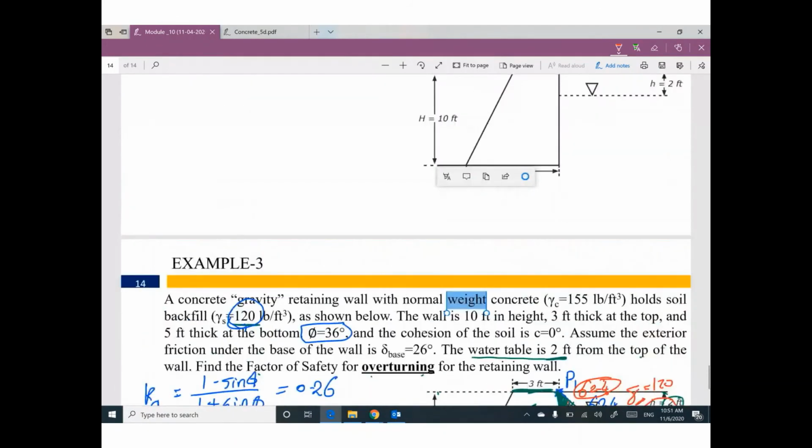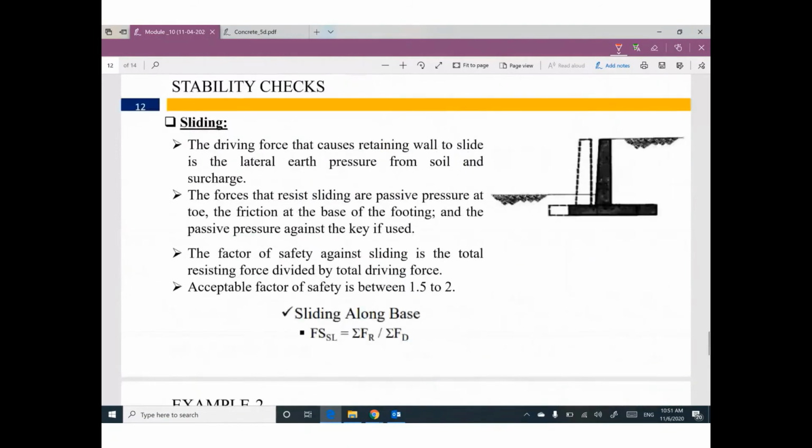Okay, we have another issue. Probably the retaining wall will not be overturned, but it will slide. It will move. No collapse will happen, but suddenly you can find this retaining wall is walking a little bit. Also, this is considered collapse, because if you find the retaining wall walked a little bit, we can expect failure. We have a house at this location, so the house will move also, because everything will be moved.